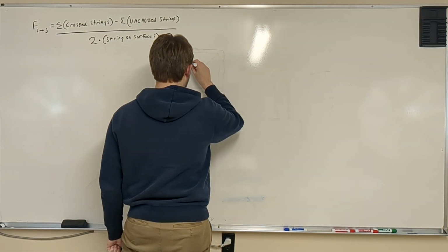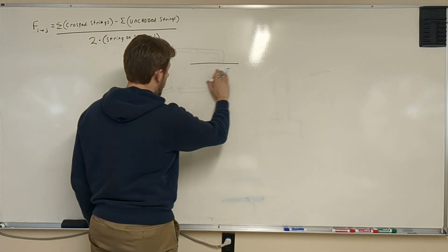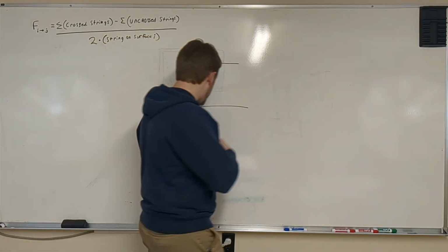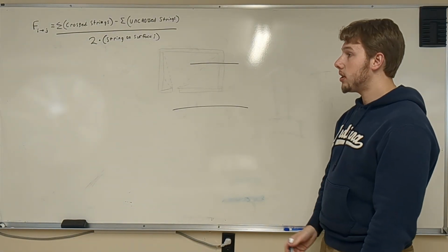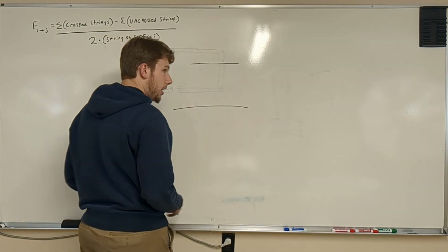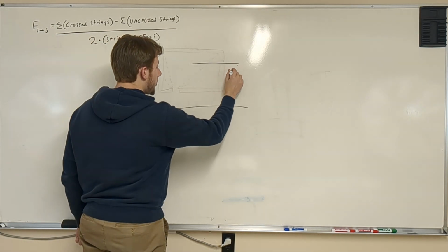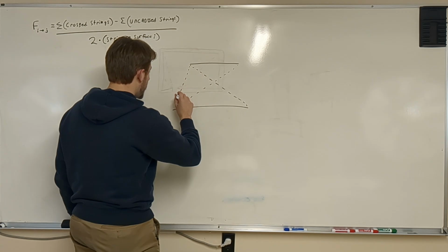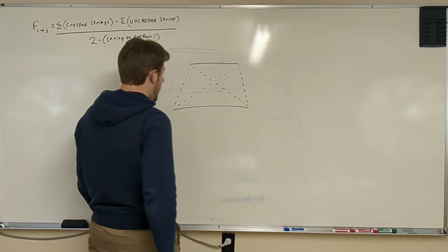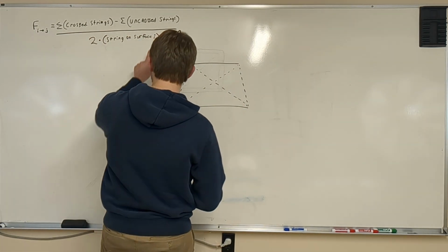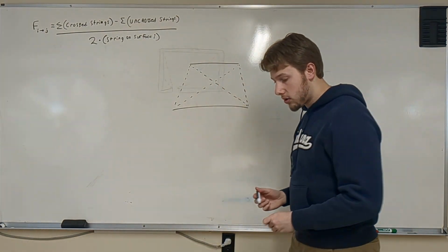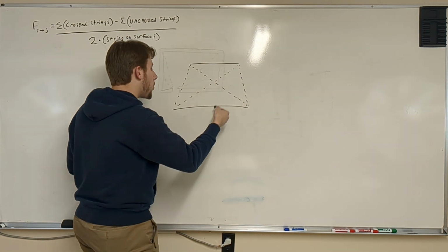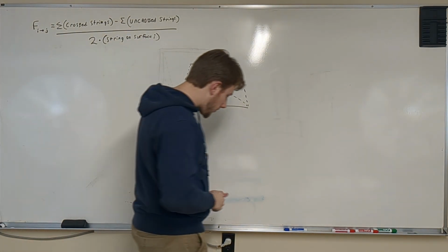So we'll take, for example, just a straight wall or just a line. Two surfaces that see each other. Then we will go and add some imaginary strings that have length related to these two that come across here. These are your crossed strings. These are your uncrossed strings. And then there is a string along the surface that you denote as i. Well, that surface is the surface that i sees j, or i sees j.